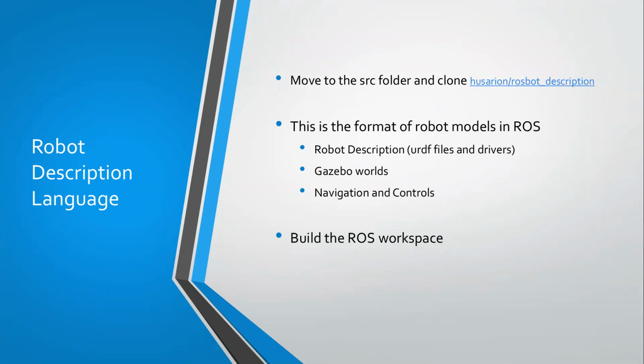Generally they give robot description, and under that they have URDF files, mesh files, or the 3D model files, and then the drivers that connect with the robot serially as well as with Gazebo and other control related stuff, like serial control that enables the connection between ROS and the robot, then drivers for connection between ROS and Gazebo models, and drivers or the other ROS nodes required to receive signals from the robot and control the robot.